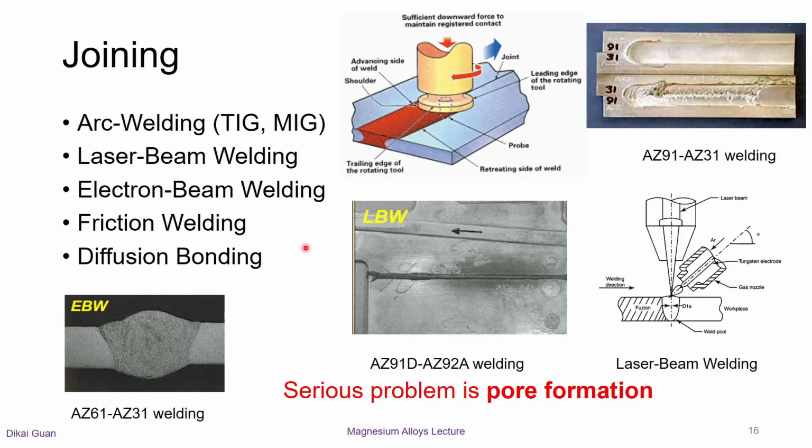In addition to the use of extrusion and sheet metal processes, die casting in particular is an especially important method of producing thin-walled, highly integrated components. The integration of die-cast components into a vehicle structure requires joining techniques that offer the maximum use of the materials of the joined parts under operating loads.